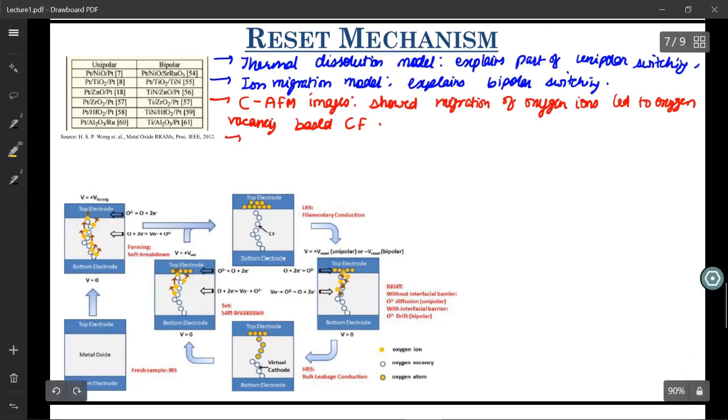And at the same time, the electrothermal simulations. So what are electrothermal simulations? You solve thermal transport along with your electrical properties, like you solve electrostatic equations along with thermal transport. So it's the same as considering the Seebeck effect along with solving the Poisson and current continuity equations.